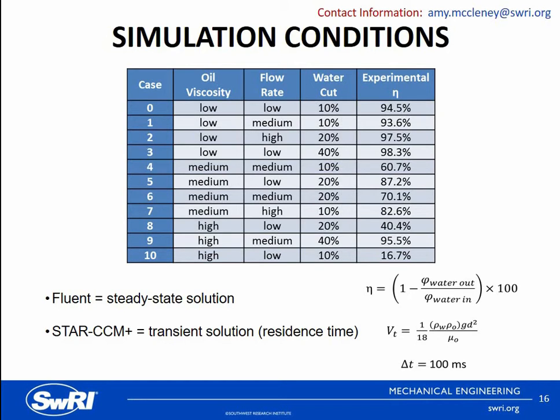The simulations conducted in Fluent were initially run using both a steady state and transient solution with the same modeling approach, to check on the solution sensitivity to an implicit transient versus implicit steady state convergence algorithm. Both cases resulted in similar separation efficiencies. However, the computational time decreased by half when the simulation was run in the steady state when compared to the transient solution. Therefore, domain discretization using 6 parallel processors was carried out using a steady state approach in Fluent in order to reduce the total solution time.